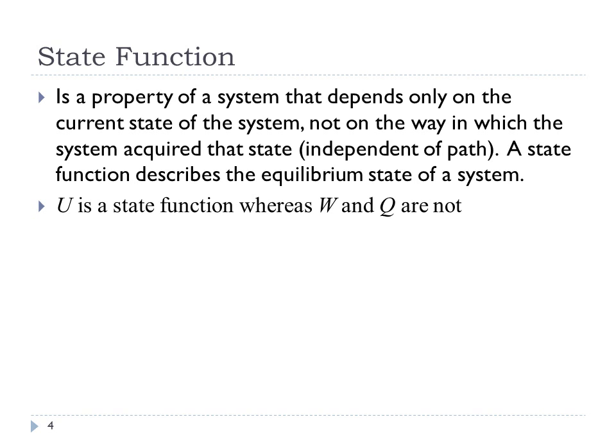If we're talking about some 1 micron by 1 micron by 1 micron region, we can define a pressure, a temperature, an internal energy. These are all state functions. They only depend on the current state of the system, whereas work and heat out of a control volume are functions of the path taken by a system, so work and heat are not state functions.